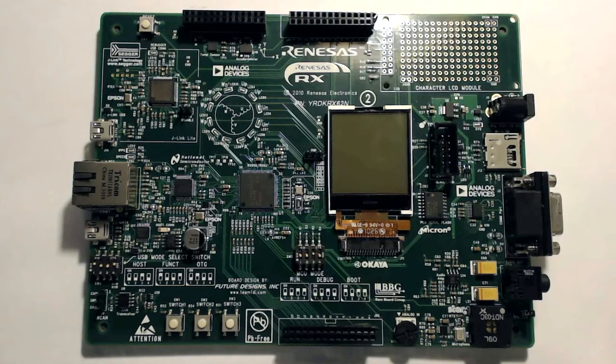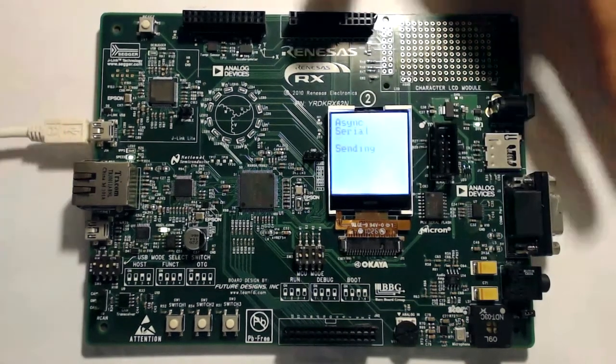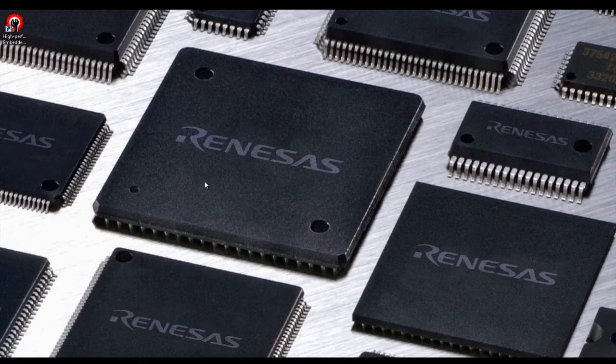In this instructional video, we'll be looking into the Direct Memory Access Controller demo for the RDKRX62N using the High Performance Embedded Workshop. Before we get started, the first thing you're going to want to do is hook up a micro USB cable to the proper J-Link module, as seen. Now that everything is connected properly, it is possible for us to load the Direct Memory Access Controller demo.